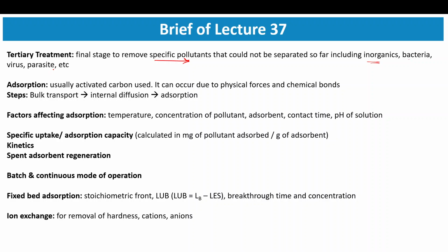Further, there could be some organics that are non-biodegradable. These could not be degraded through the activated sludge process or biological treatment, so in that case these organics also require some tertiary treatment.